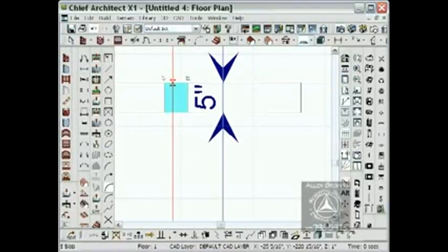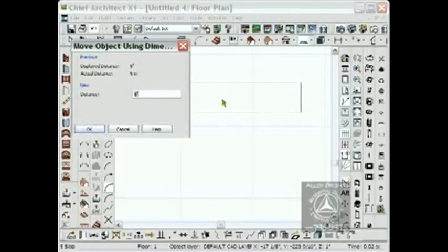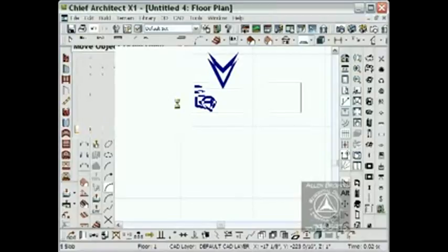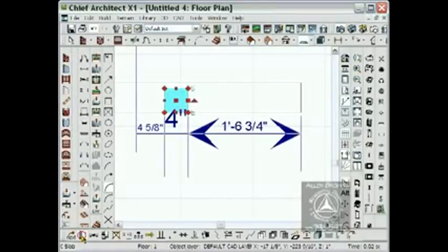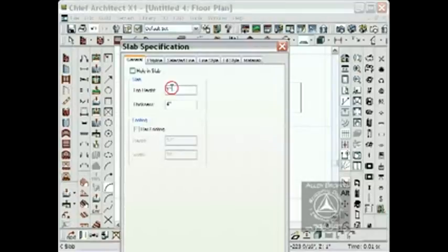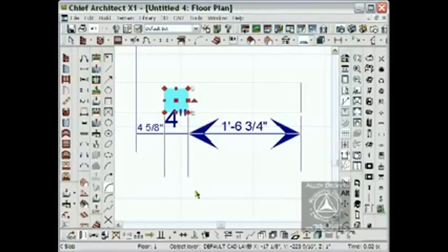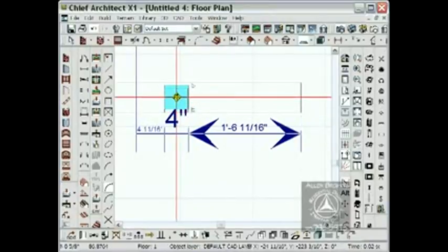Now there's a couple of different tools you can use to make this pole. You can use framing members, you can use polyline solids, you can use slab. A lot of ways you can do it. Now I want to open that up. And top height, I want that to be about 60 inches. Thickness, 62, so that it goes down into that slab a little bit. Click OK. Center that up a little.